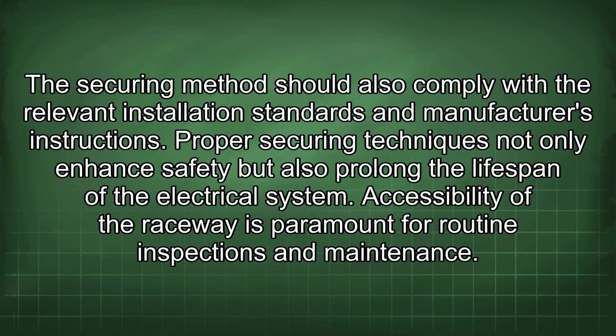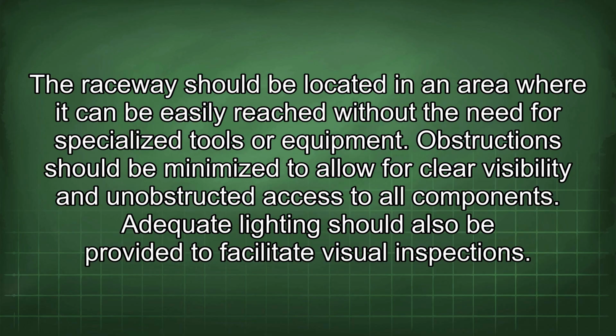Accessibility of the raceway is paramount for routine inspections and maintenance. The raceway should be located in an area where it can be easily reached without the need for specialized tools or equipment. Obstructions should be minimized to allow for clear visibility and unobstructed access to all components. Adequate lighting should also be provided to facilitate visual inspections.